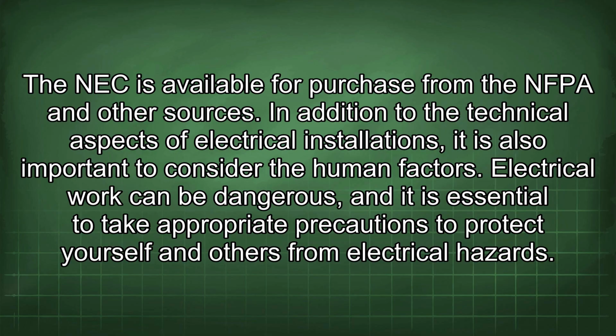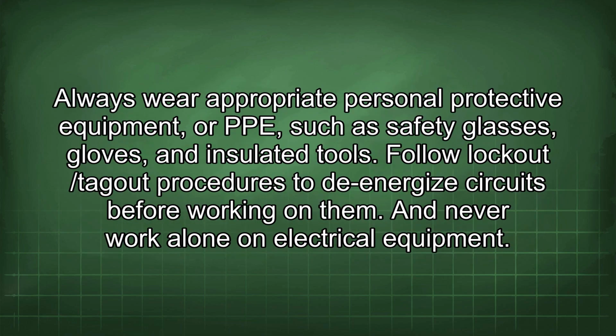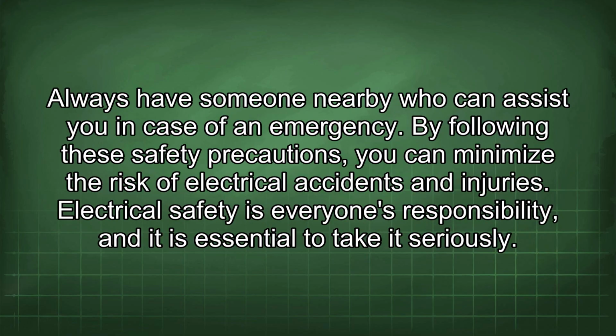In addition to the technical aspects of electrical installations, it is also important to consider the human factors. The electrical work can be dangerous, and it is essential to take appropriate precautions to protect yourself and others from electrical hazards. Always wear appropriate personal protective equipment, or PPE, such as safety glasses, gloves, and insulated tools. Follow lockout/tagout procedures to de-energize circuits before working on them. And never work alone on electrical equipment. Always have someone nearby who can assist you in case of an emergency.